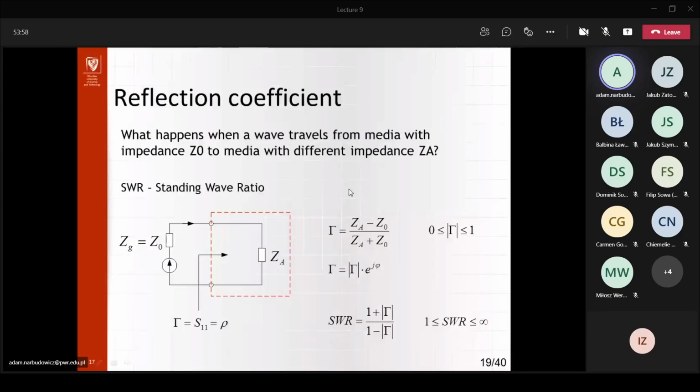All right. Well, okay, the answer actually is exactly on this slide. Typically, if we have an electromagnetic wave moving from one boundary to another, you should know that if there's a permittivity mismatch, there will be certain reflections. And the very same phenomenon will be observed with electronic circuits. As I tried to explain already, the Maxwell equations are very generic.